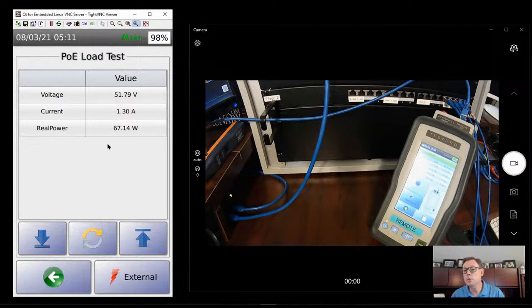You can check into the switch port and see if you're actually getting the power that you need at the switch port. Maybe the switch port is not provisioned properly. Maybe an end user purchased a 90 watt 12 port PoE switch for $50, and you're going to get what you pay for.